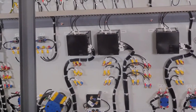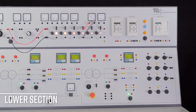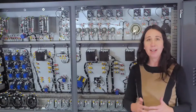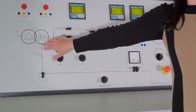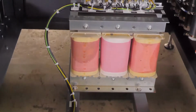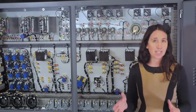Moving on to the lower panel now. This trains students on more advanced three-phase power distribution topics. It features 2 three-phase transformers, lines and load banks to simulate a medium to low voltage distribution system. One transformer, the line power here, reduces the voltage from the incoming laboratory mains supply to the correct value for the experiments.